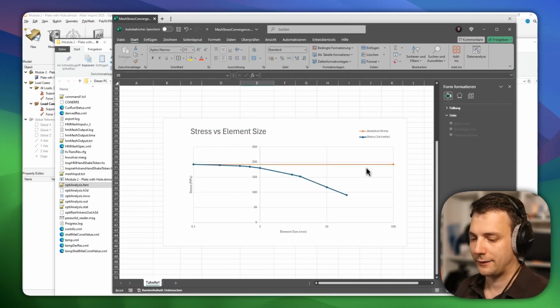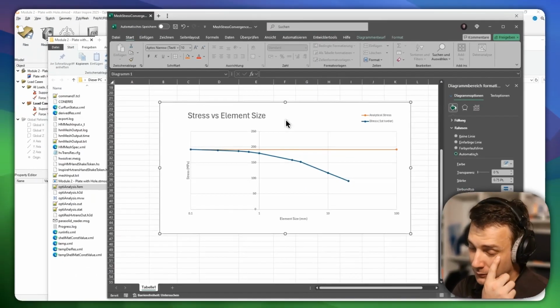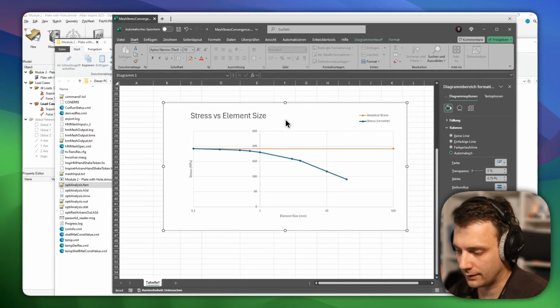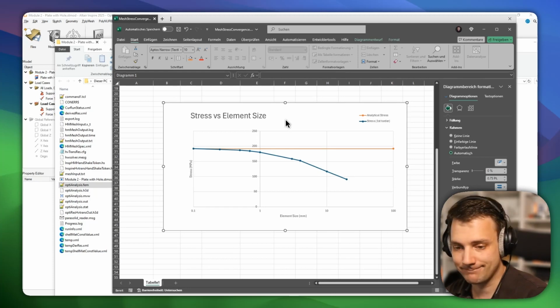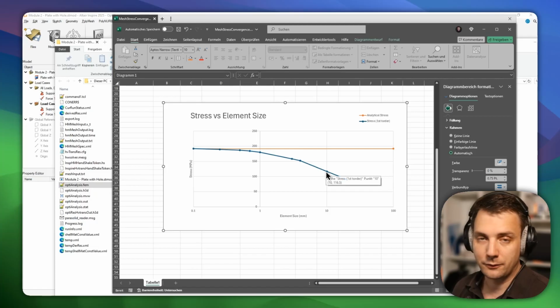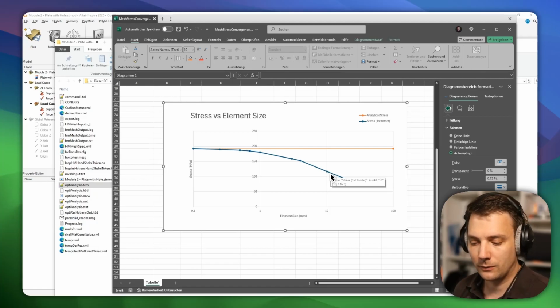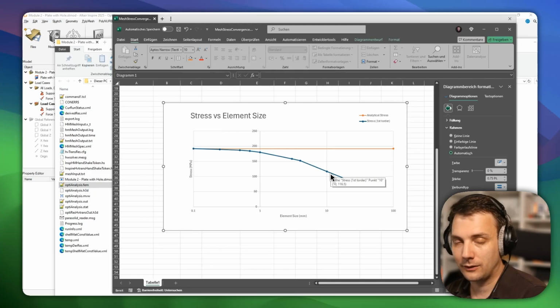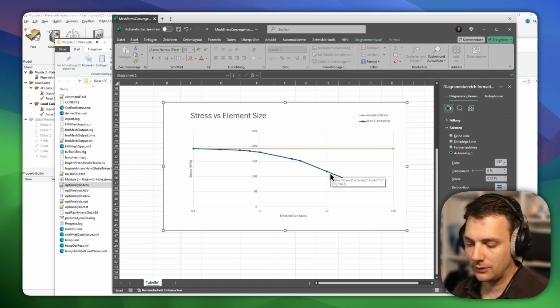All right, what do we have here? So this would be a mesh convergence study. It's pretty standard in industry to do something like this, and it's not gonna get you anywhere. It's wrong. It's off by more than 50%. It's just bad. Okay, so this is our starting point at 20 millimeters. So basically what I just then did is run with 10. Okay, it increased. Whenever you see that the stress is increasing by a considerable margin, then you just keep on decreasing the mesh size in this area until you get to a converged state. And this is what you see here.